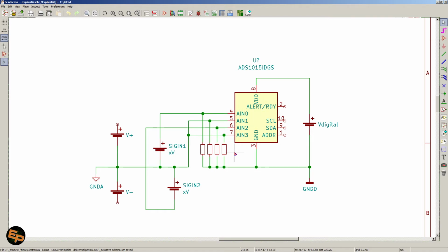Okay, we're not supposed to do that. The ADCs don't like negative inputs whatsoever, and they actually have some internal diodes, Schottky diodes, to clamp these voltages and protect themselves against negative voltages and so on. But anyway, overall, it will most likely not break the ADC, but it will definitely make the ADC not evaluate those voltages correctly. Okay, and that's a problem. So this is a big no-no.